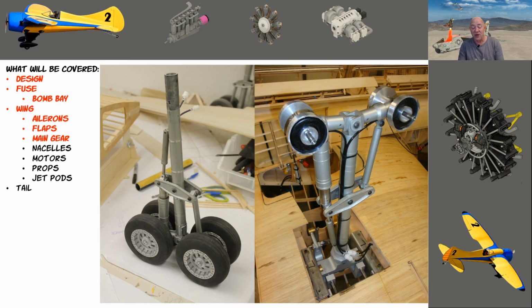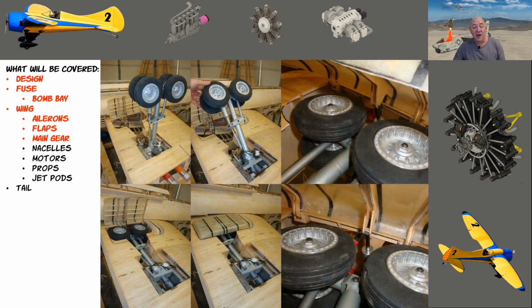So they had brakes on them. Everything about this landing gear when it was done was just super sexy. It worked great. But I basically replaced all the stainless steel in it with carbon fiber. And as you can see, it worked great. I had a sequencer for the landing gear door there. The wheels came from Glennis, which I don't think's around anymore. It's really sad, but Glennis made the best wheels at the time.